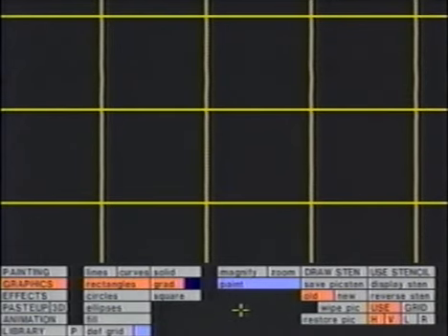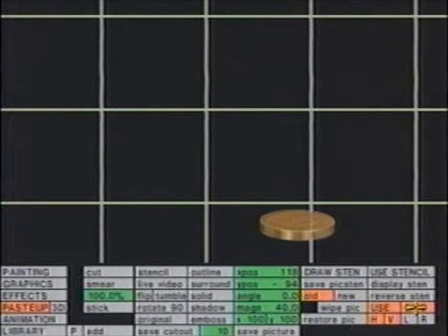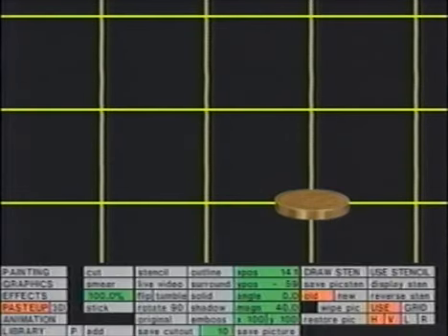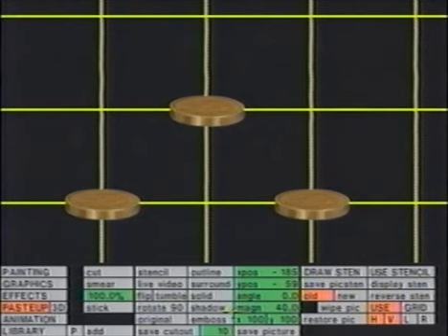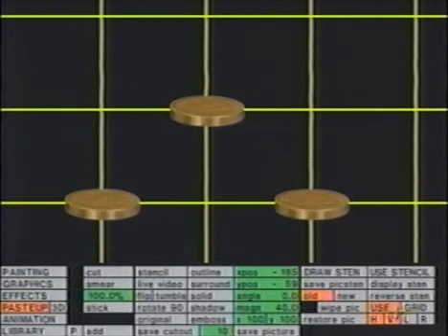With Use on, we can, for example, use the grid to define the exact position of a graduated rectangle. Over one square, over several squares. Using the same grid in Paste Up, Use Grid will restrict the position of the cutout to the grid cross points. Alternatively, by using Center, the cutouts can be positioned in the center of the rectangles.